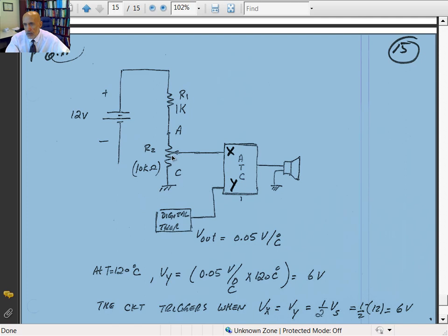You've already noticed that every time you connect a small resistor in parallel with your voltage divider, or your potentiometer as a voltage divider, it has a tendency to lower the voltage and creates inaccuracy in your system. You're loading down the circuit. To avoid that, there are ways you can do it, maybe later in the semester we might get into this.